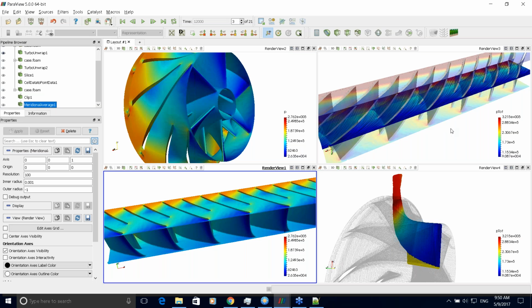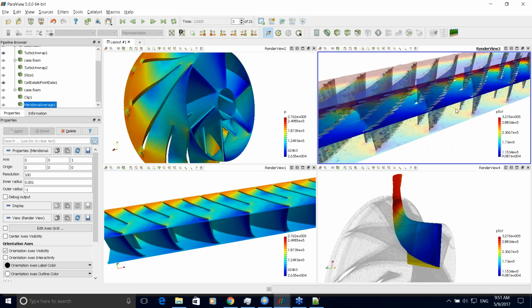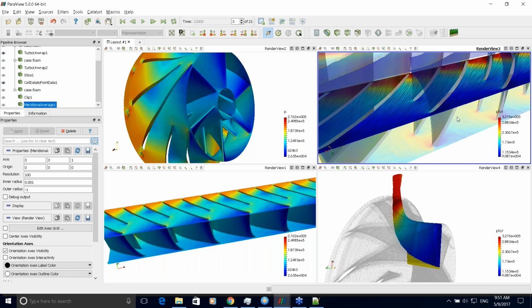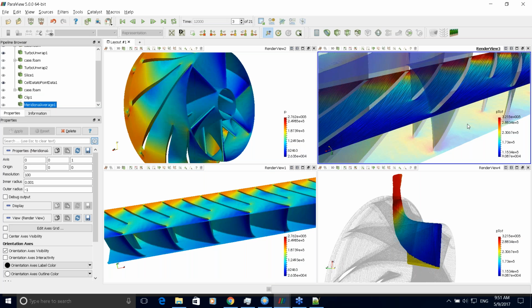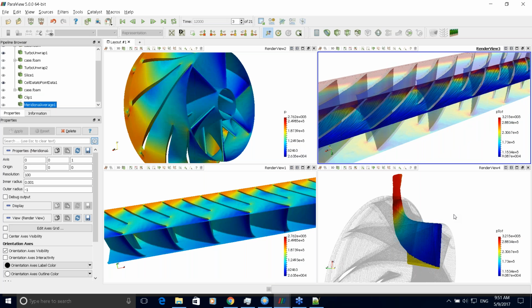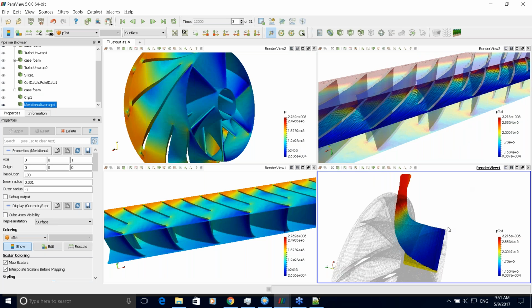You can create a radial slice at any radial coordinate of the blade, and visualize the streamlines with total pressure distribution. Moreover, you can also create the meridional average on the blade with, for example, total pressure distribution. All this can be done directly in ParaView.